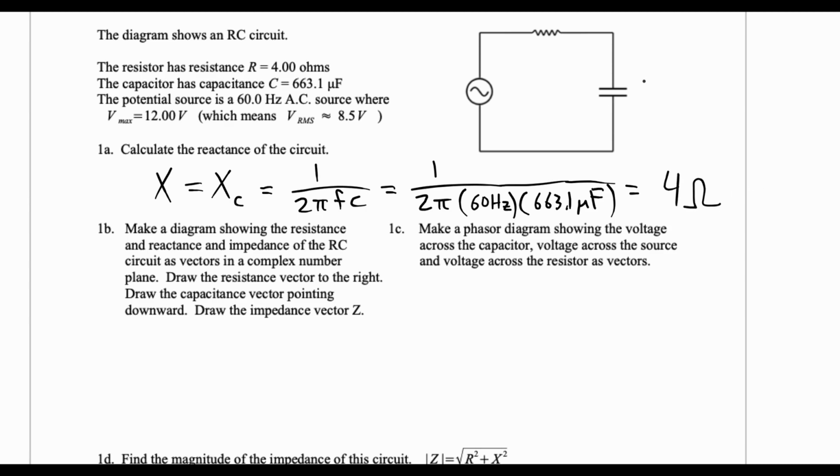And so the capacitor is going to contribute 4 ohms. And the resistor is also 4 ohms. So we'll each contribute 4 ohms at this particular frequency.